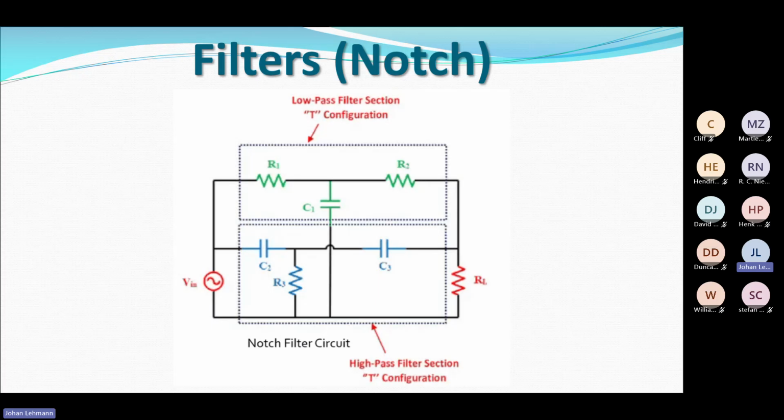They will have a very, very high reactance, the same as this one. So this C1, because it's got a high reactance, doesn't really feature at low frequencies. It's only the two resistors that feature when I do the low pass of my frequencies.